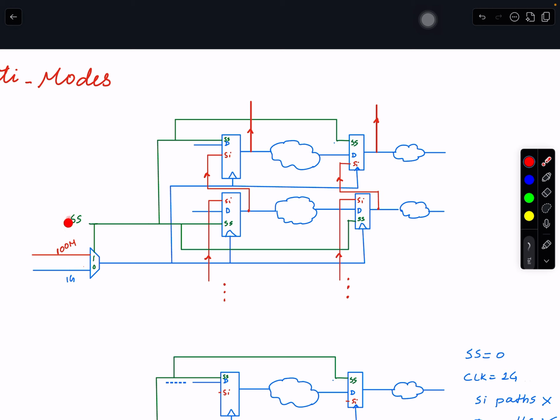Did you define any case analysis in the situation that I'm talking about? No, I didn't set this to 0 or 1. So this is just like any other signal here. The tool is thinking it is making a rise and fall transition, and it can be 0 or 1. So with that condition, both clocks are coming here. Now keep in mind their clock frequencies are different.